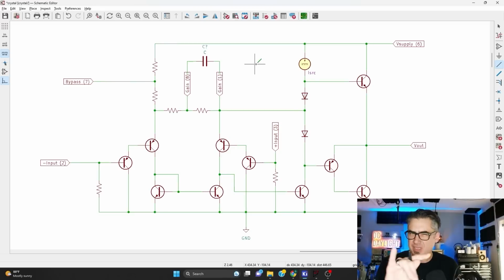If you look in the data sheet, I think if you bypass, you end up with a gain of like 200 instead of 20, which is kind of common. So you're bypassing components using the proper value of capacitance, and we have a bypass capacitor. So it just so happens that I bought a couple of these LM386 amplifiers online, and we can take a look at that on the bench, plug it in, and see if it works.